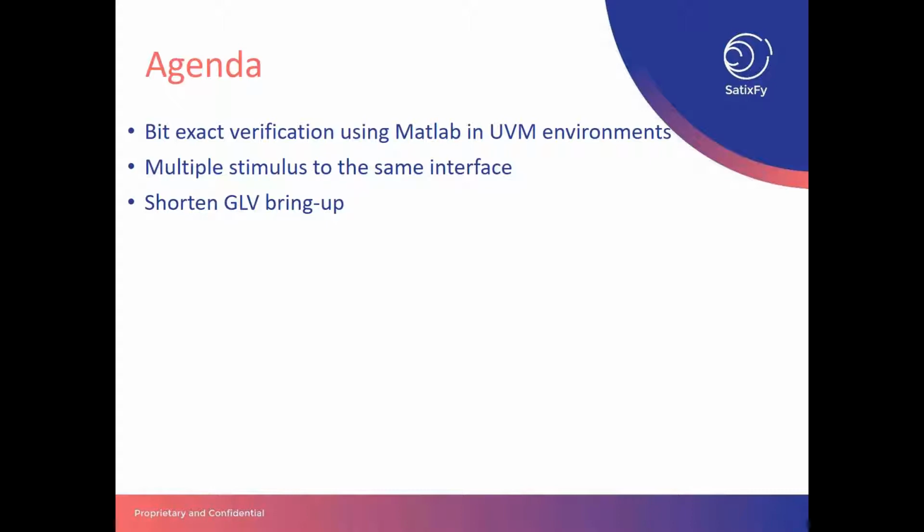The 3 challenges that I want to present: first, how we do verification using Matlab reference models in UVM environments. The second challenge will be how we can, on the fly, generate stimulus on the same design interface from different sources, like a VIP or the design itself. And the third one is, in case you have to do gate level simulation and you can't avoid them, what you can do to make it a bit easier.